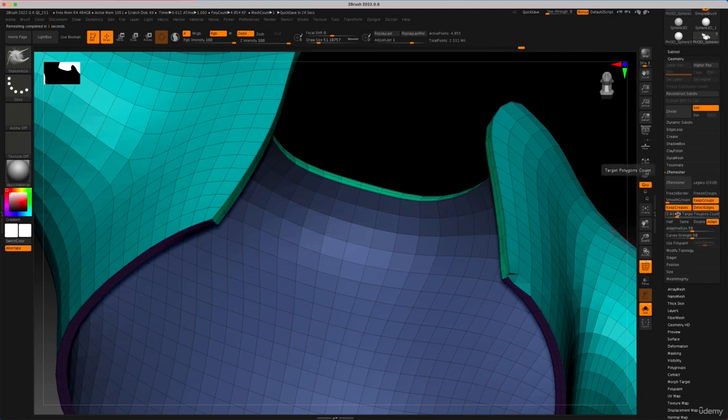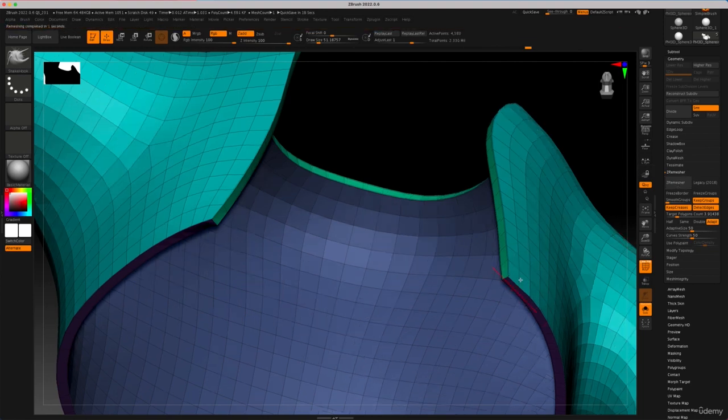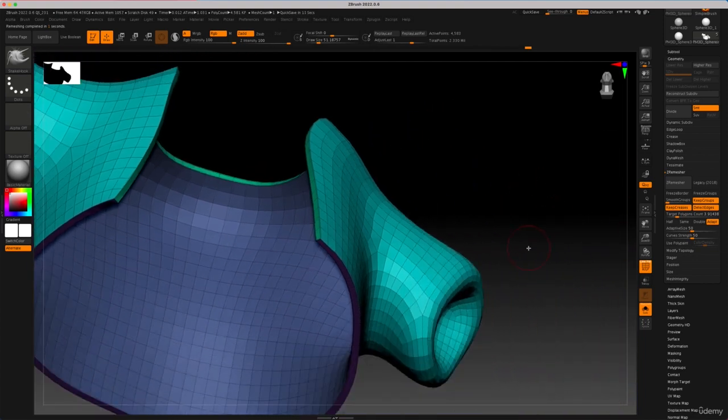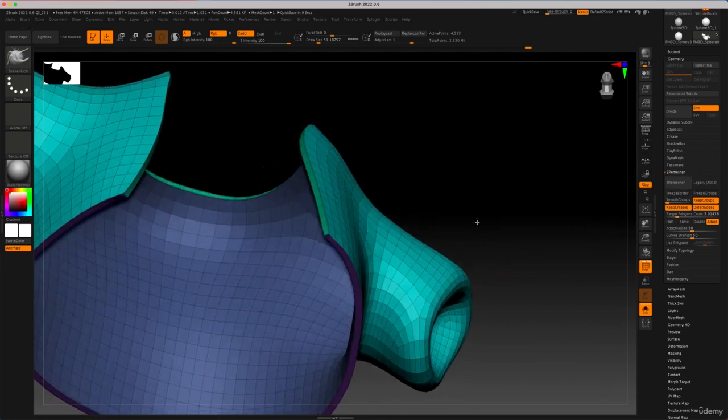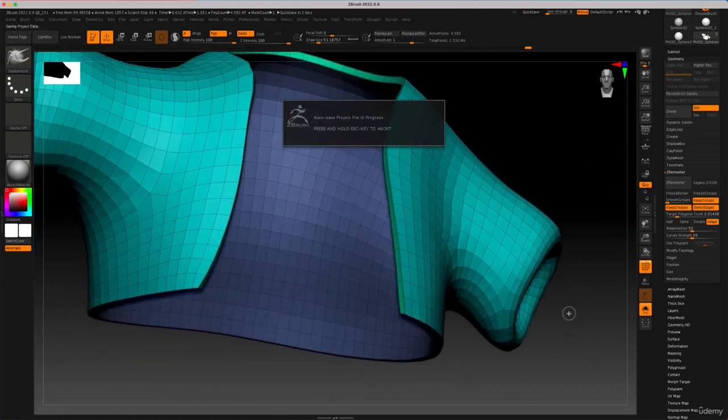One thing I do is change the target polygroup so that it can go through and find something clean, and you kind of saw the progression of how I worked that out. If you try it like four or five times and you're still not getting what you want, go all the way back. Maybe start with a different polygon count to get your way out there.